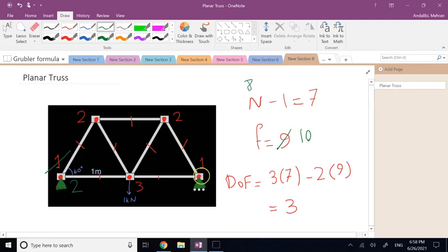And what about here? That's right, you have a pivot, but that pivot is now added to a roller. So this contact point can do this rotation, and it can also move horizontally. The only thing it cannot do is go up and down. So here you have one contact actually.